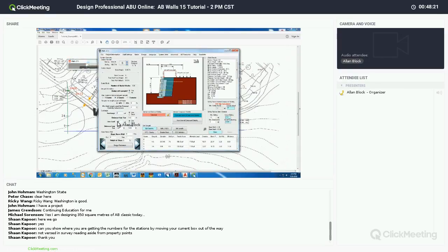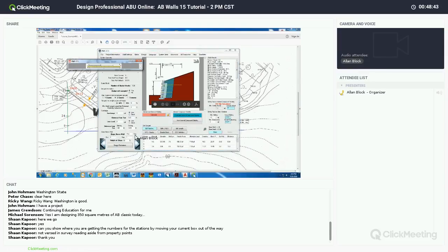To move on to the slopes, I'm going to zero these all back out to our standard flat top wall. And I'm now going to apply a slope by using the area in the bottom left-hand corner. You can either go by degree of slope, or you can go by rise and run, whichever one you know. So I'm going to do a 3-to-1 slope. And when I hit calculate now, it's going to apply a 3-to-1 slope above my wall at 50 feet in height. That is just a reference for us to assume that it's a continuous slope beyond the wall, or at least the wall influence.